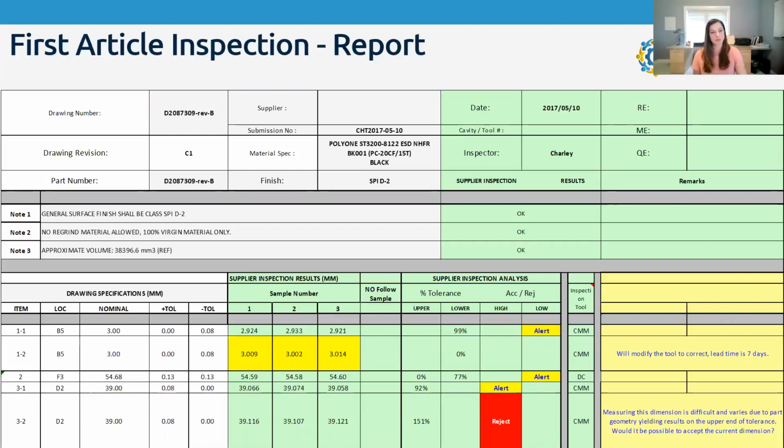So Jesse, a question in from the audience is, what tools do you use for inspection? CMM, CT scan, et cetera? Yes, it depends again on the type of feature. There's a lot of different tools we use. On CMM, yes, of course. Sometimes scanning, so digital scanning that can allow us to compare the part to the CAD file, and sometimes that's a stoplight type of thing where you have the green, yellow, red. There's also, of course, hand tools. Calipers sometimes are the cheapest, fastest, and sometimes the most accurate.